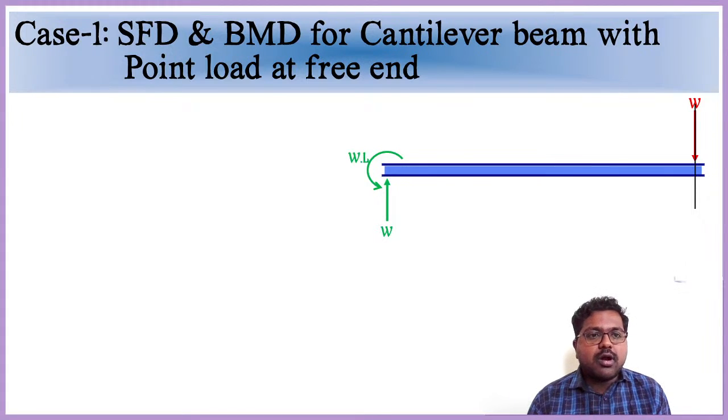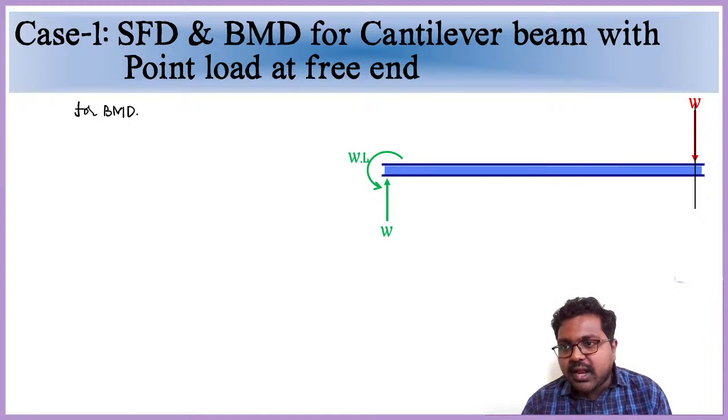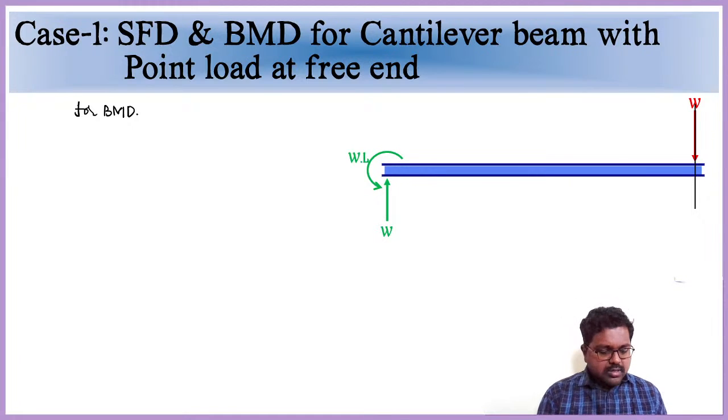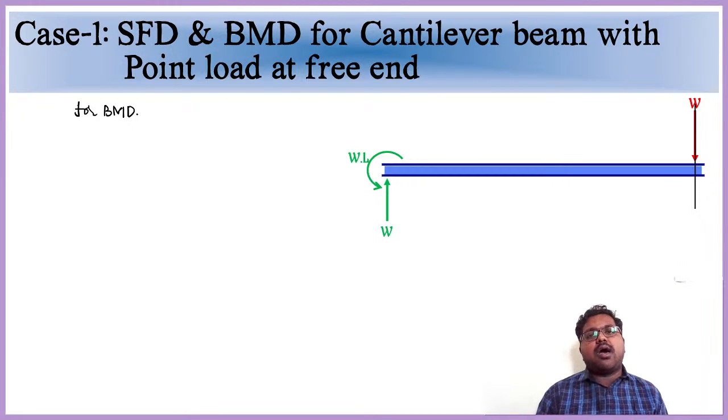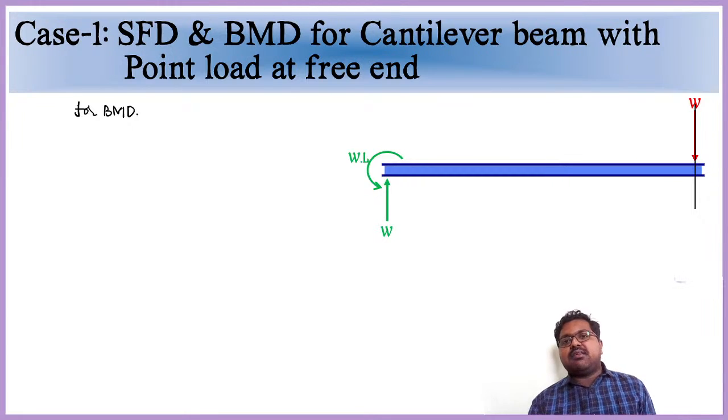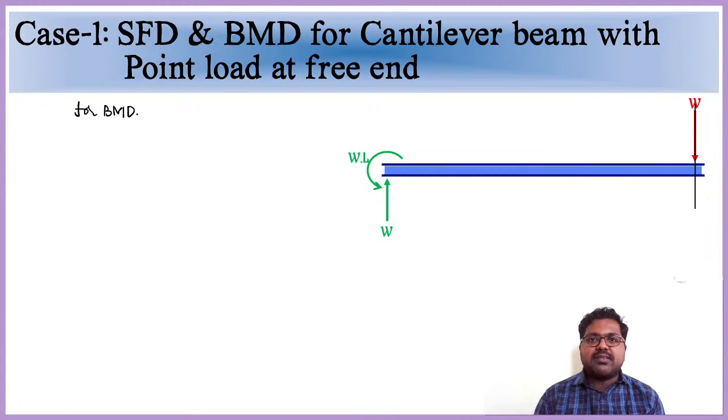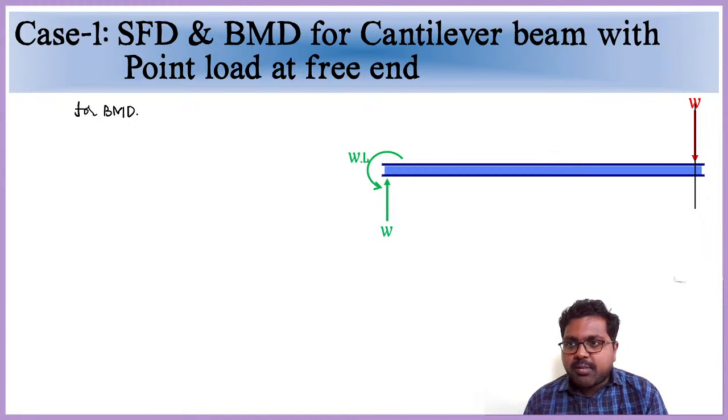Okay. Then see, next one, for bending moment. Okay, we got the shear force diagram. Now for the bending moment diagram, what do we need to do? Again, I am considering the same portion. See, if we have considered shear force from the left hand side or right hand side, it is better to conveniently take the bending moment also from the left hand side or right hand side. It will be easy for you to calculate the things. So I am considering again from the right hand side.